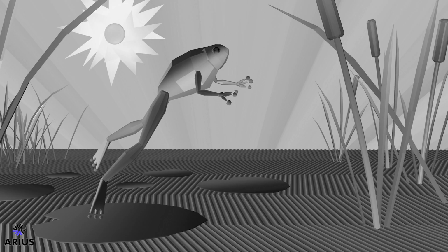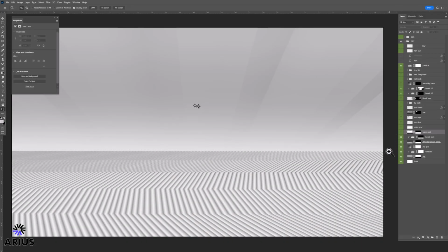After converting the image to black and white, the frog body does not follow logical gray tones in terms of elevation, and the resulting gray tone of the waves will not produce a smooth undulating surface. In this case, it's necessary to create a custom wave gray tone independent of the color pixel values. Simply apply a gradient to the 3D object and render out a new element. Unlike with the frog, this will work as there are no hidden sides to apply the gradient tone. It could also benefit with a gradient extending to the horizon.